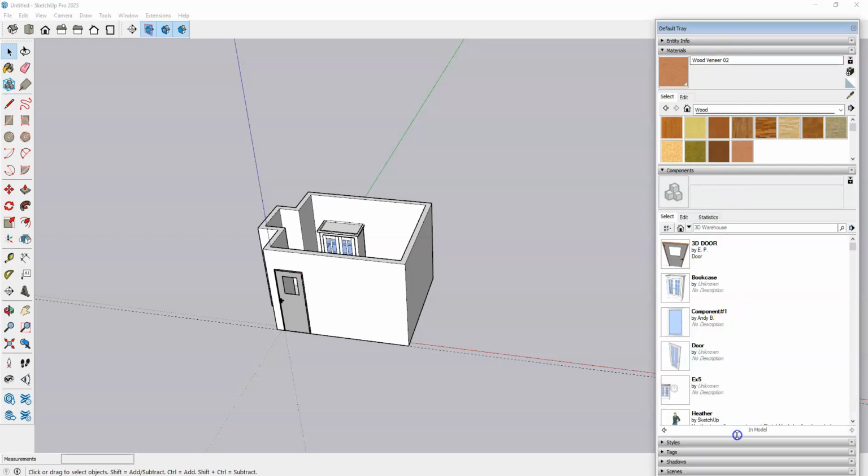And then over in this components browser, every component that you have brought into your model will stay in this components browser. You'll notice even though I deleted Heather, the scale figure, she's still in my components browser. It still stays in the model even if you have deleted it from your model space. Sometimes, if you've been importing a lot of different components and ended up not using it, that can also slow your file down a bit. So it can be helpful to purge the unused ones, and this will get rid of them entirely from your model so that they're not slowing your model down.